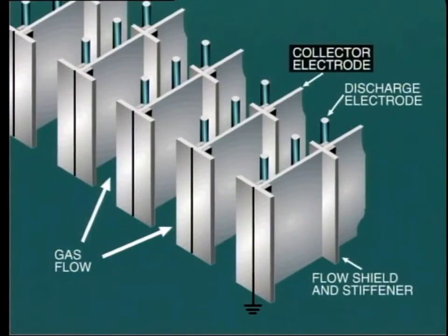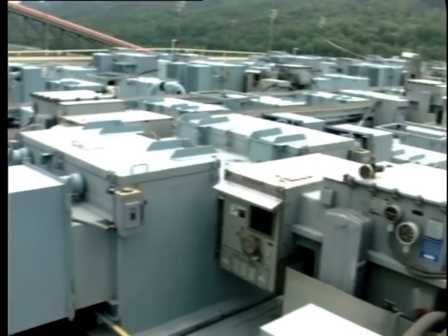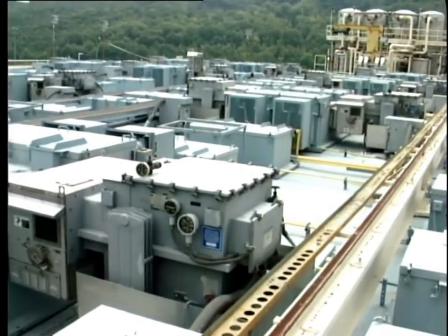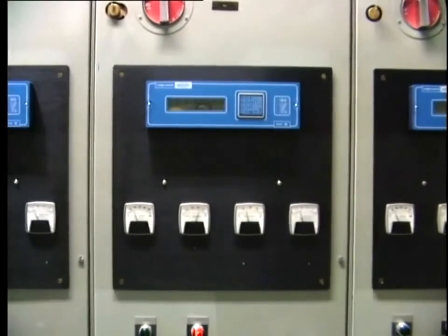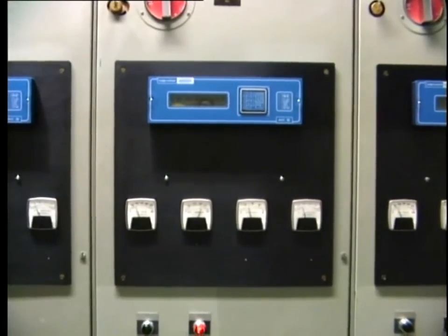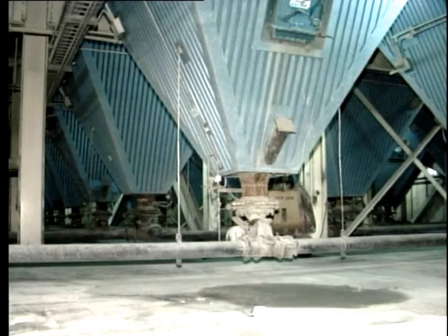Multiple collector plates are built in line with the gas flow and fixed solidly to the frame and outer box, which are all grounded. The negative electrodes, often known as discharge electrodes, are located between the collector plates in the gas passage. The high-voltage DC supply is obtained from transformer rectifier units, which are usually mounted on top of the precipitator. At frequent intervals, the plates and electrodes are mechanically rapped so that the removed dust falls off into the collection hoppers below. The ash hoppers are not designed for storage, therefore the ash must be removed almost on a continuous basis.